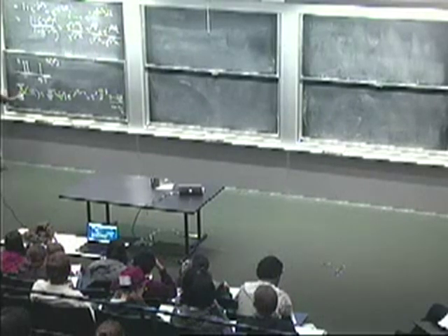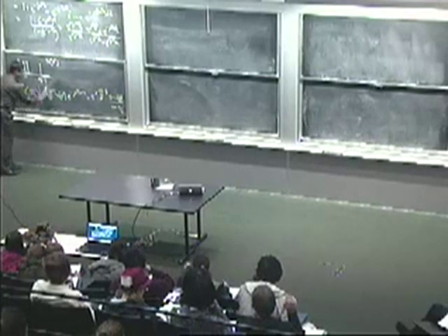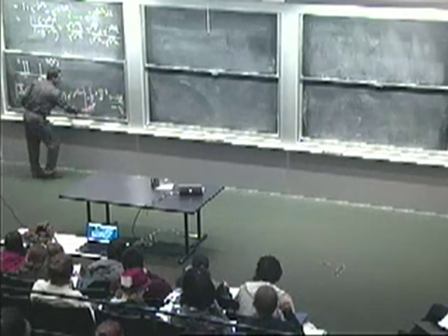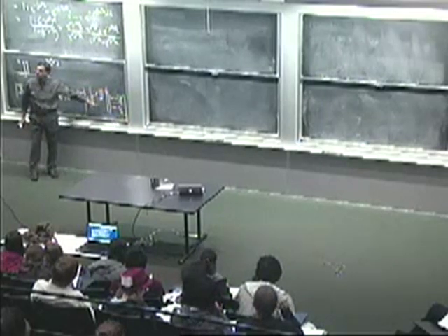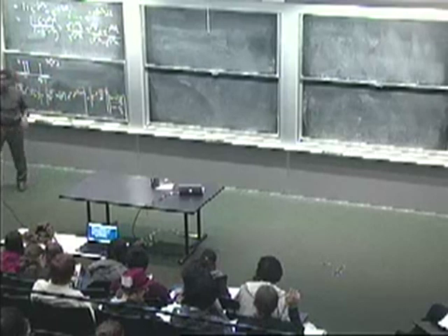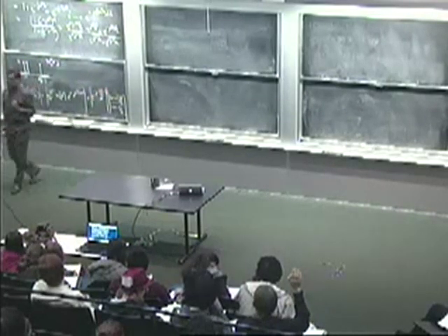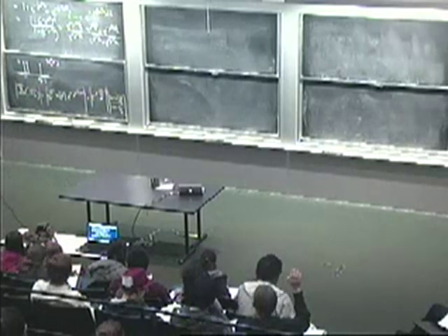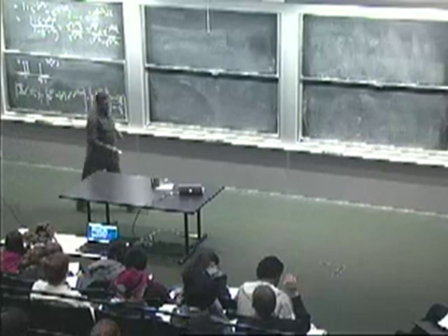If I wanted to get the magnitude of this, well, the magnitude of this is going to be the magnitude of this piece times the magnitude of that piece. What's the magnitude of the first term here? Just 1, right? It's e to the j something, so its magnitude is 1. So here's the magnitude of the DTFT. So that's the spectral characteristic, and that's something that we can plot.